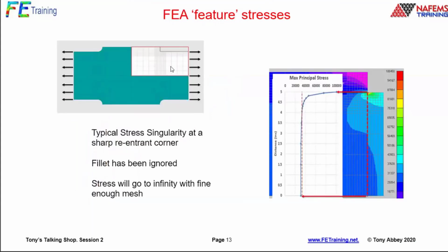Here's a stress concentration, and this is a classic shape. It's a shoulder. So there's a known stress concentration factor where I've put the curved fillet radius in. Deliberately here, I've taken that fillet radius out, defeatured it. And now we've actually got a mesh-dependent stress level. So this is my FEA feature. If I forget to defeature, or I deliberately defeature, then I'm going to get very high stress in here.